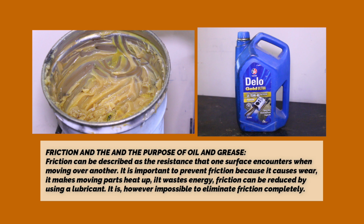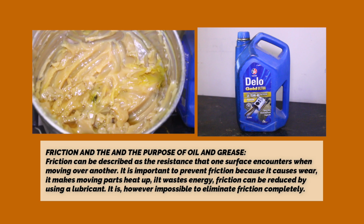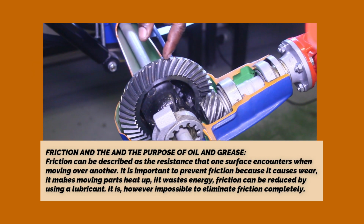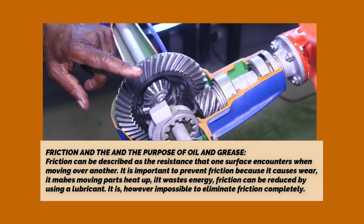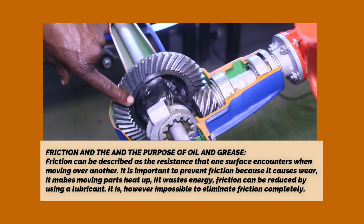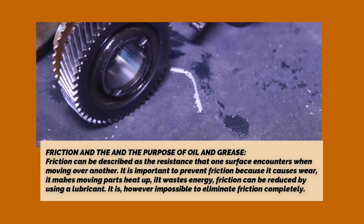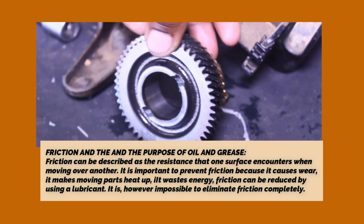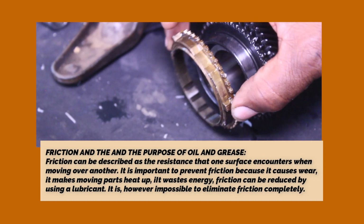Now that we have the objectives, let us get into today's lesson. The friction and the purpose of oil and grease. Friction can be described as the resistance that one surface encounters when moving over another. It is important to prevent friction because: 1. It causes wear, 2. It makes moving parts heat up, 3. It wastes energy. Friction can be reduced by using a lubricant. It is, however, impossible to eliminate friction completely.